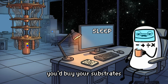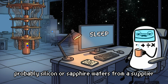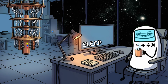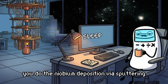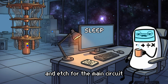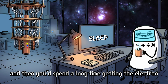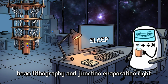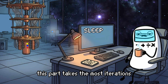You'd buy your substrates, probably silicon or sapphire wafers from a supplier. You'd do the cleaning steps. You'd do the niobium deposition via sputtering. You'd do the photolithography and etch for the main circuit. And then you'd spend a long time getting the electron beam lithography and junction evaporation right. This part takes the most iterations.